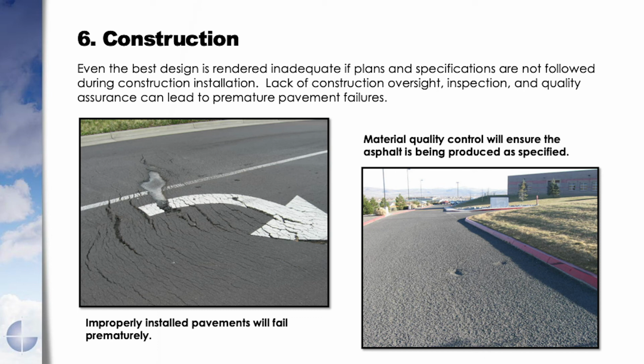So there's not a lot of recourse to have the contractor come back and repair these kind of things after 1 year. So that makes it extra important to make sure that you are inspecting the initial installation to make sure it's done properly, but also before that 1 year runs out, do a visual inspection of the new pavement and look for these telltale signs of premature failure.